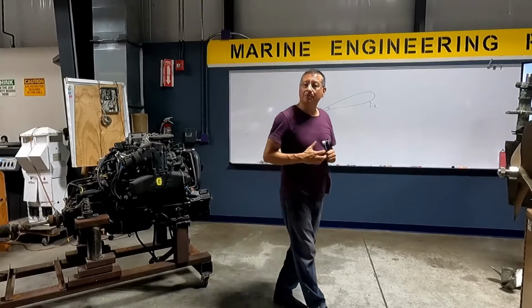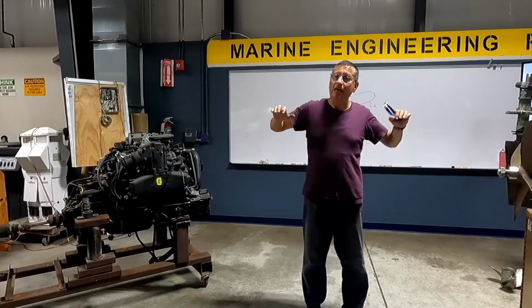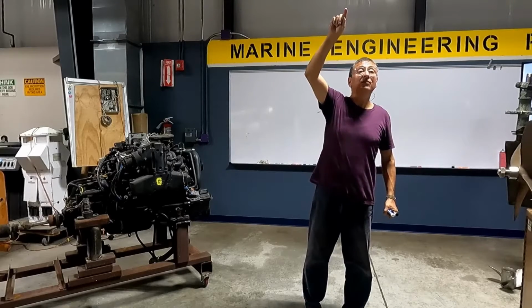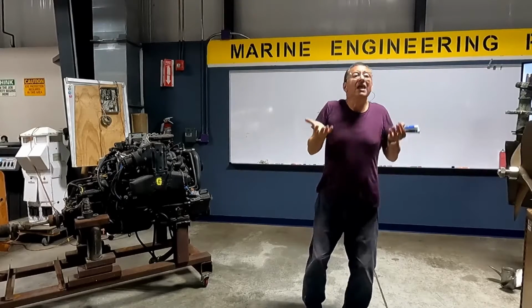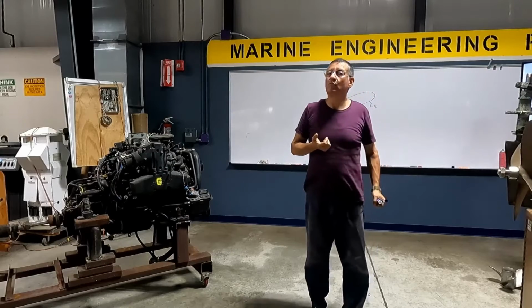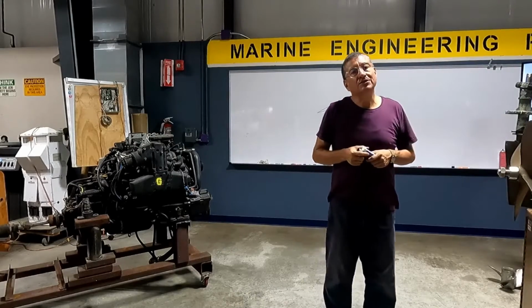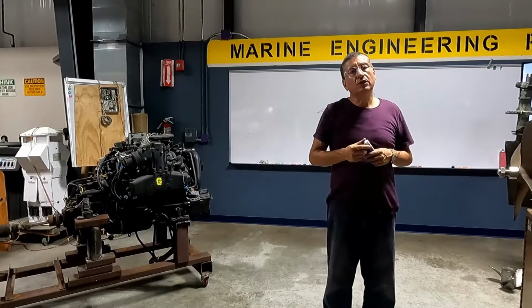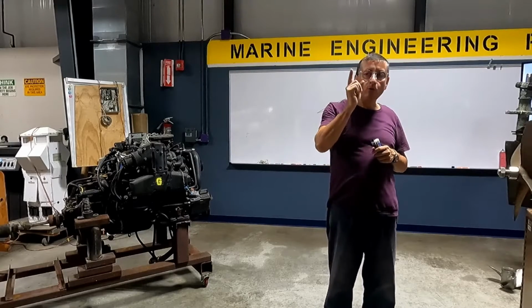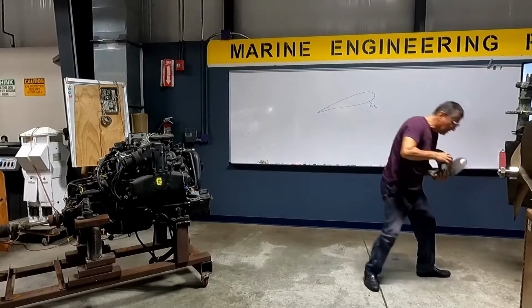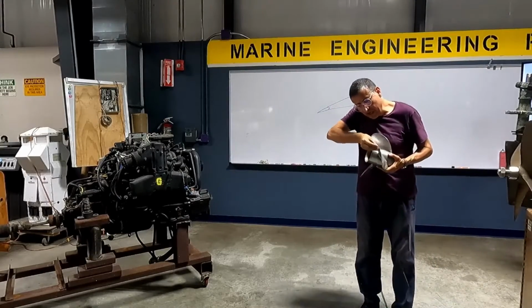And you remember I explained that in airplanes, they incline the leading edge to increase the lift, the sustentation, more lift. In a marine propeller, this is not possible. For that reason, some propellers, especially outboard propellers, come with a little inclination here.